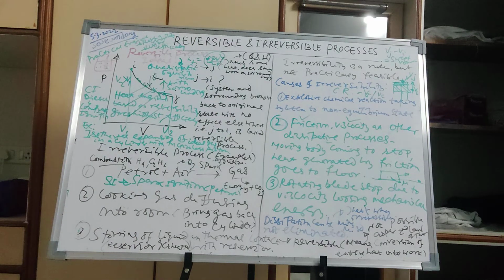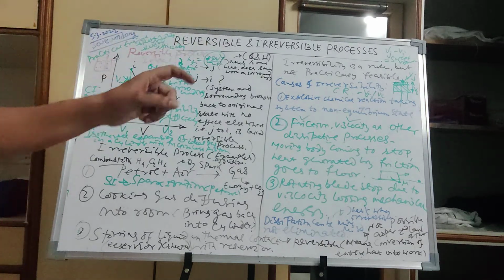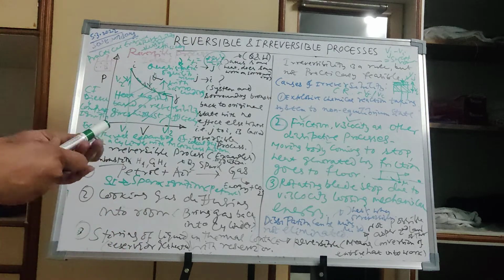When a pressurized fluid is passing through a pipe, there will be a frictional loss. Whatever the pressure at end A, at the other end B you will not get that pressure. There will be a pressure loss, called frictional loss. It depends on the length of the pipe and the diameter of the pipe.